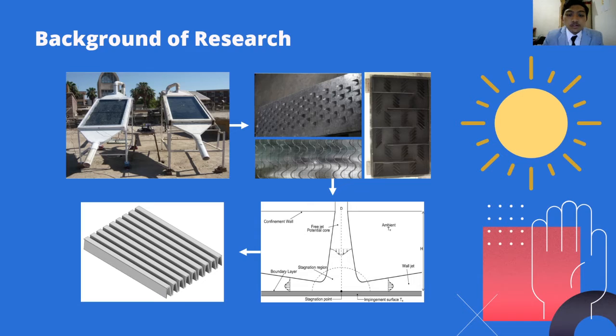This makes a lot of research conducted with the aim of increasing the efficiency of SAH. Modifications made to increase the thermal efficiency of solar air heater are to increase and expand the absorption area of heat energy. There are various types of modification, like the addition of planes, fins, obstacles, vortex generators on the SAH. After adding the plane area, the researchers also made variations for the area that had been added to SAH, namely in terms of shape, angle, size, or distance in the SAH installation, especially on the absorber plate.